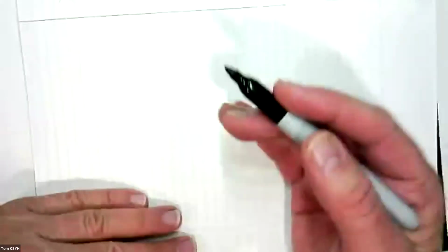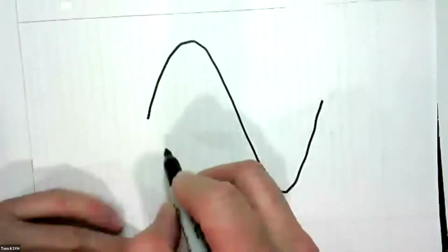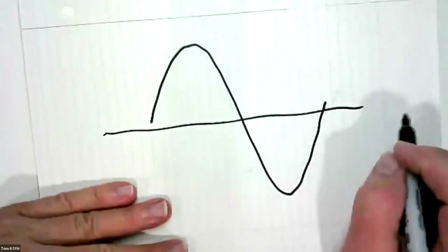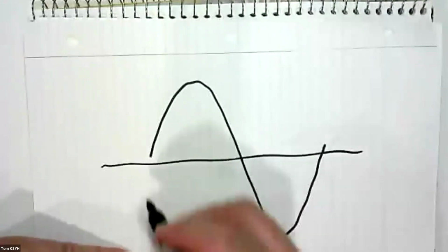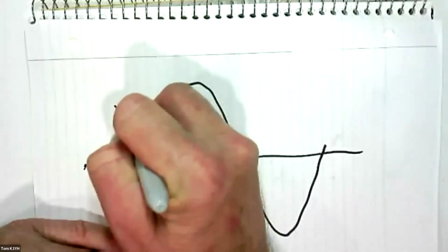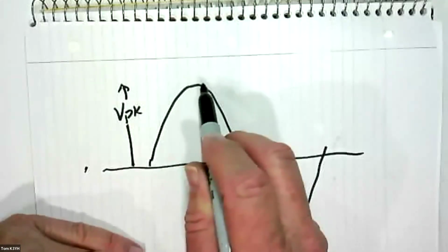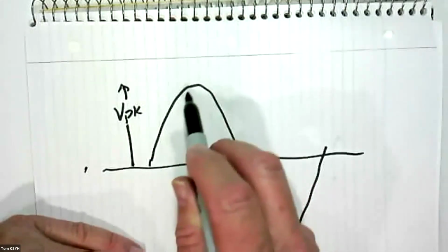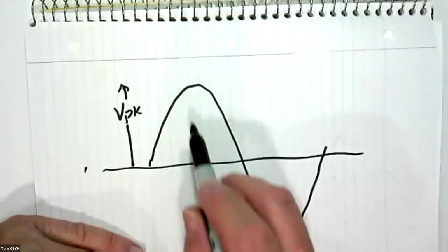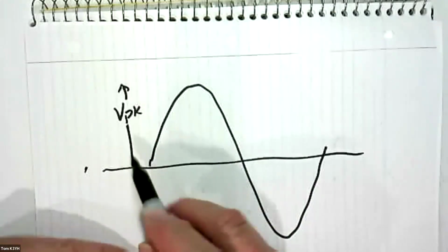There's a sine, and what I'm going to tell you right now is only for sine waves, so keep that in mind. So here is one cycle of a sine wave, okay? And there's three voltages. The peak voltage, I'll just call that V peak, PK, is the top of half of the cycle here, from 0 to the maximum amplitude. That's called the peak voltage.